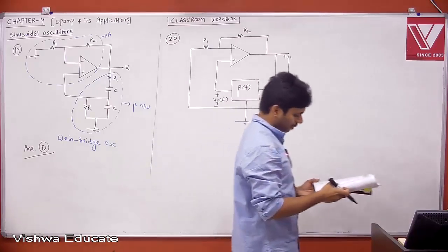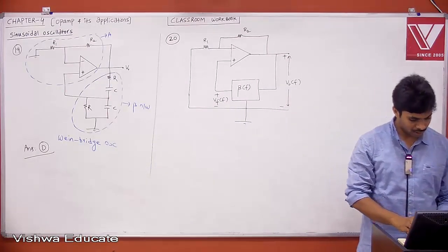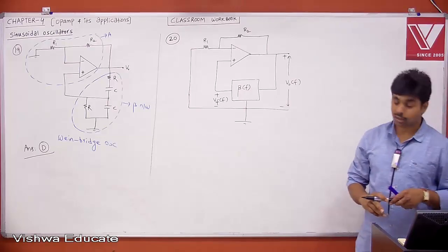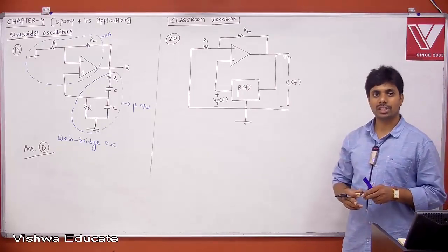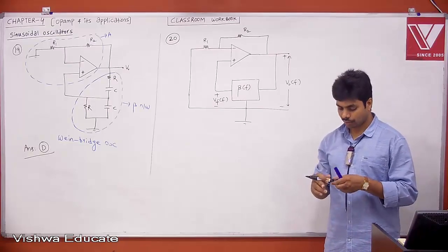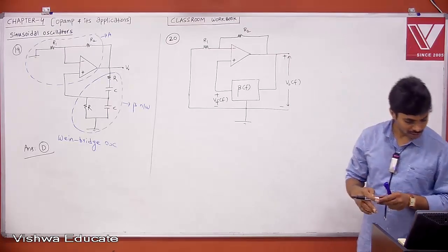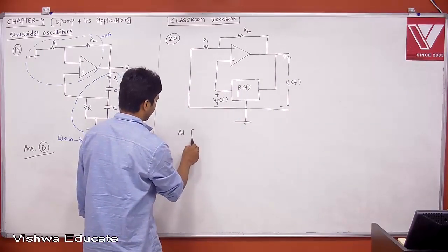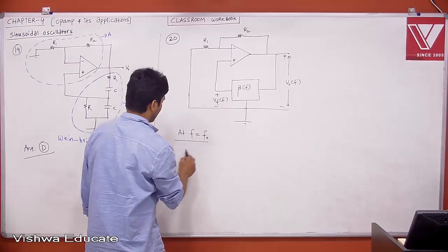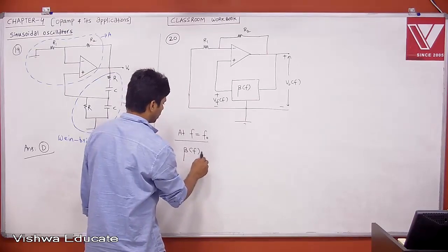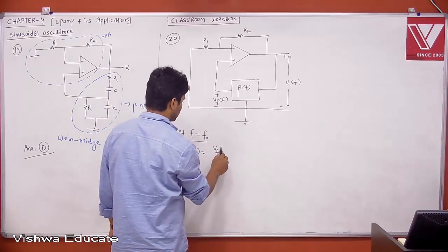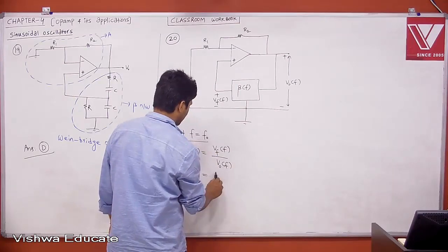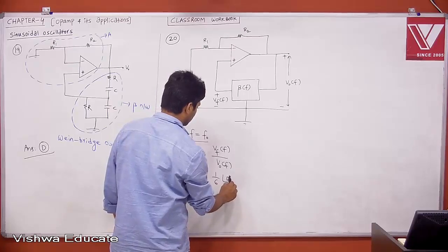Now this is the block diagram given, saying that it is employing positive feedback and is intended to generate sinusoidal oscillation. And if you observe clearly, he has given beta of f at f equal to f naught, the resonant frequency, the feedback quantity Vf of f divided by V naught of f, which is 1 by 6 at an angle 0 degrees.